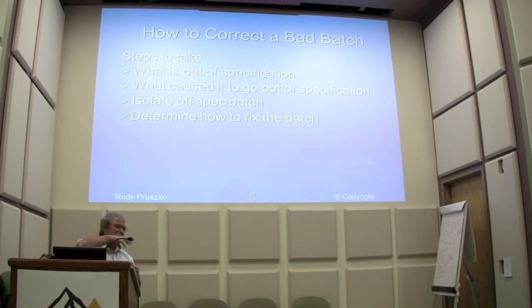And if you're adding methanol that you didn't take back up to 99 or 98% purity, if it's only 95, there's another 5% water. Now all of a sudden you have 2,000 parts per million of water going in. That's a lot of water. That's going to inhibit the reaction. It's going to make FFAs, take out your catalyst. So that's where a lot of the problems come from.